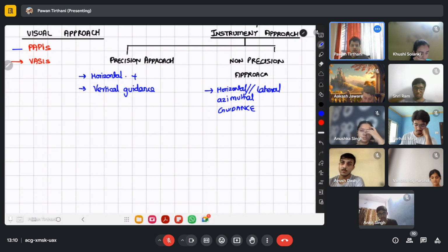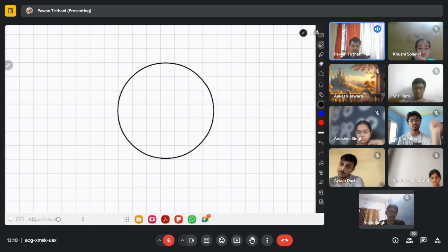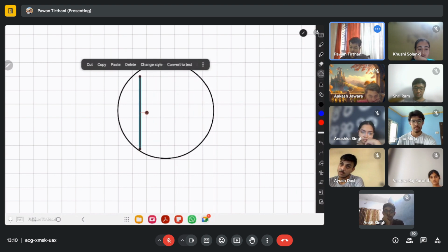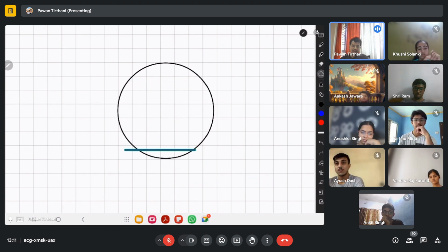Plus, it also gets vertical guidance. So, the deviation instrument, the D bar, you saw a D bar which was vertical and it could move like this. We also have another D bar which can tell you like this. It can tell me, okay, now I'm very, very up, I should go down. I'm very, very down, I should go up, fly down, fly up, fly down.